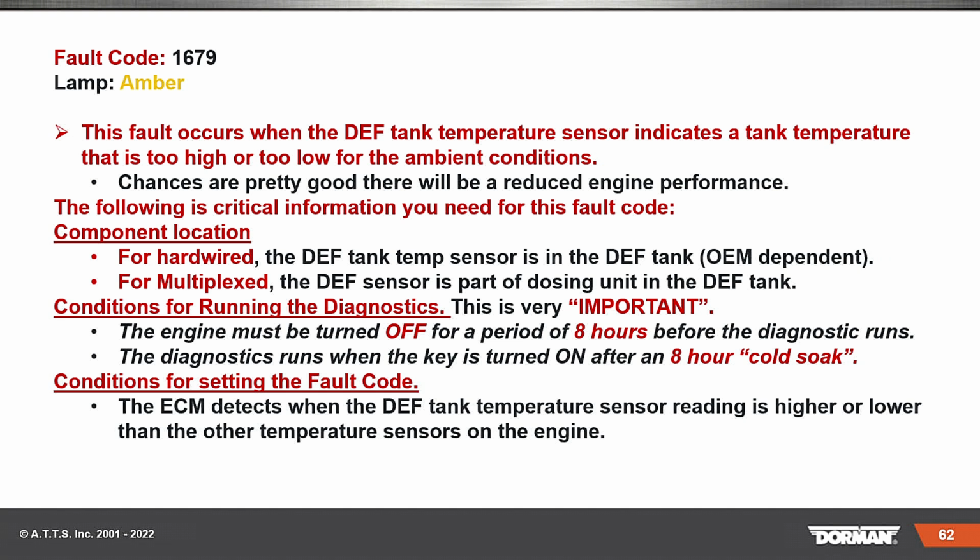If you've got a hardwired, the DEF tank temp sensor is in the DEF tank. Nice to know, right? And again, OEM dependent. For multiplex, the DEF sensor is part of the dosing unit. So we got a couple of choices in here. However, this part right here, condition for running the diagnostics. The engine must be turned off for a period of 8 hours before the diagnostic runs.